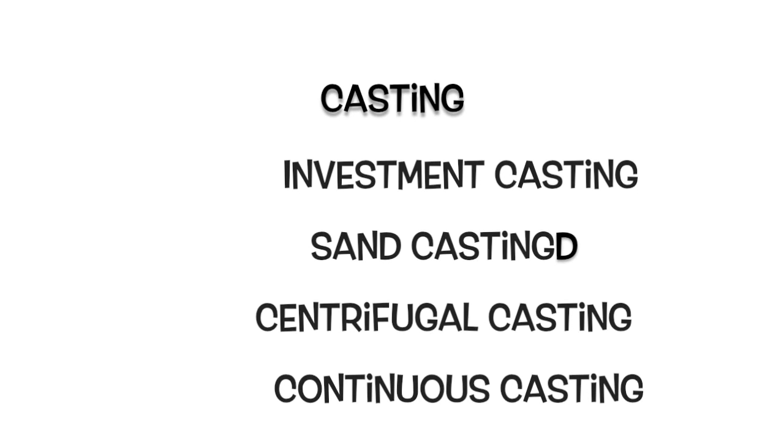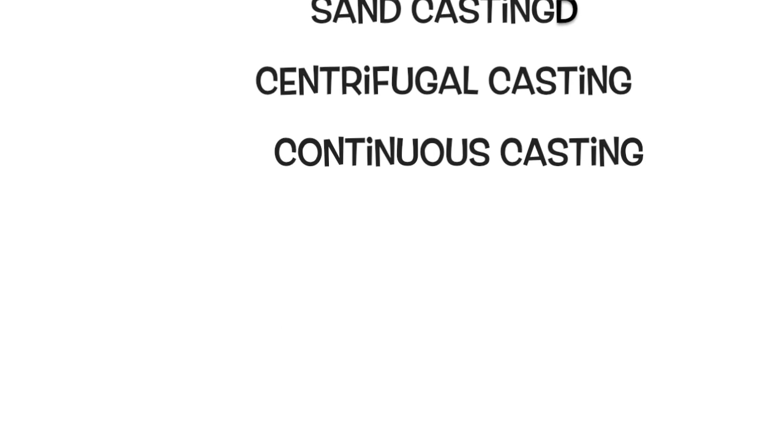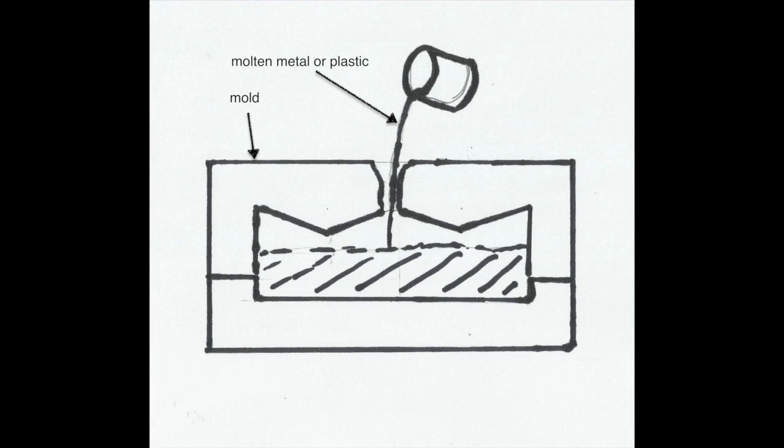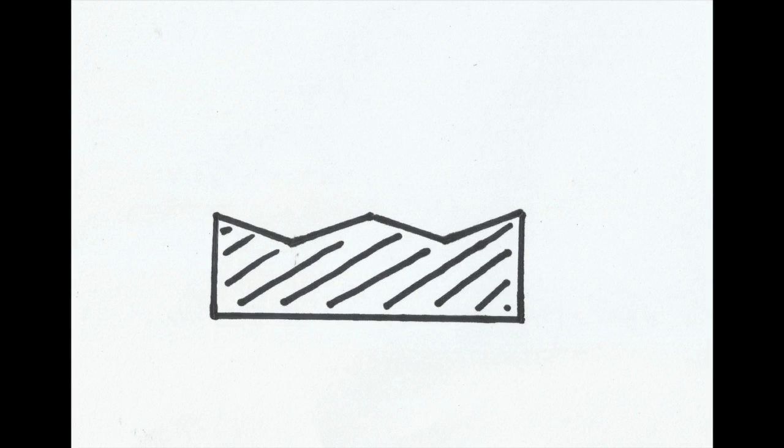Casting. There are different types of casting methods, but each one is used depending on the materials and the intricacy of the shape that needs to be achieved. However, they all follow a similar method where molten metal or plastic is poured into custom molds. This is then allowed to cool and harden, giving it a shape that is very close to the size of the final product. Casting is more suitable for constructing parts that require internal cavities or more complex geometry. Such parts include carburettor housing or holding brackets, which have a specific shape to accomplish a specific task.